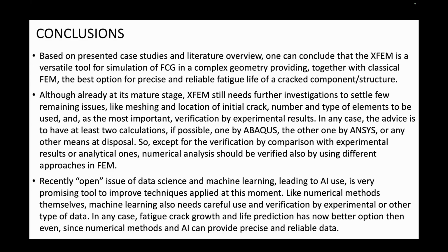But then phase three, think about it again, we concluded it is a coincidental or statistical or whatever, a matter actually of material heterogeneity. However material is good or component is well made, it's still a bit heterogeneous. So where crack would grow in real material depends very much on material inclusions or any other defects, and it can change the path due to its microstructure or defects or heterogeneity.